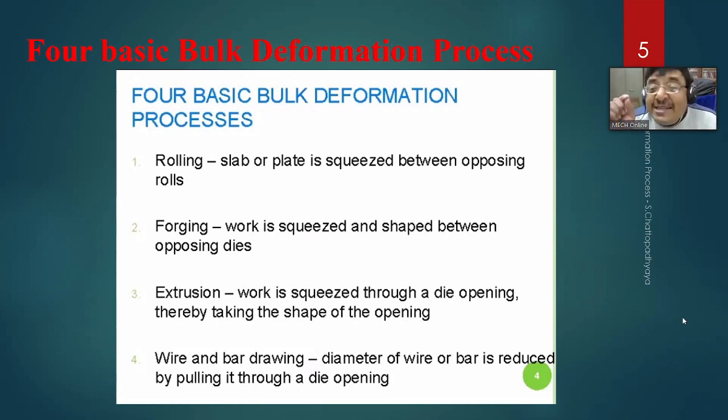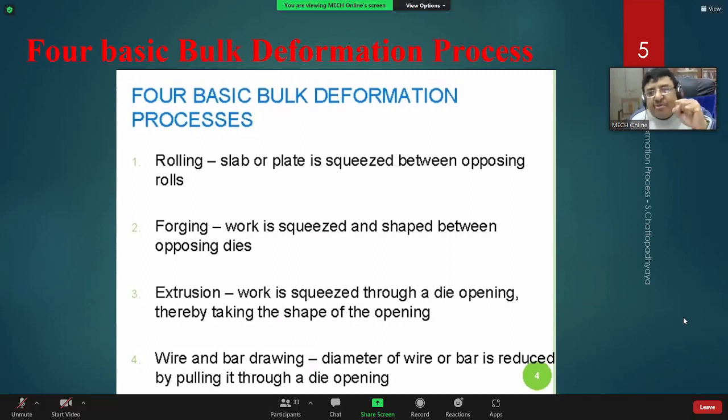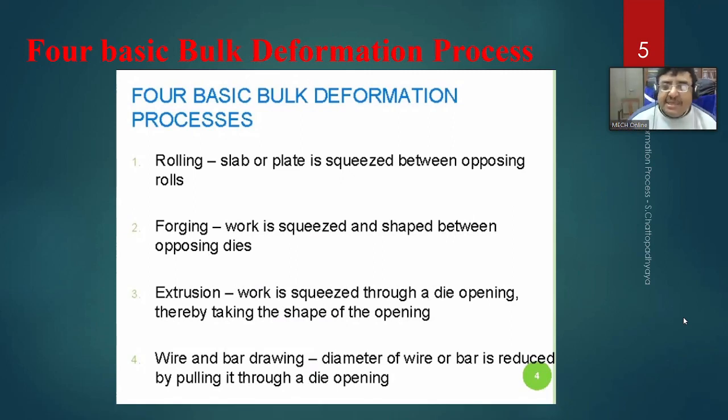So iterative process. Wire drawing is an iterative process, step by step. Suddenly you cannot just go for that amount of reduction, step by step, stage by stage. Otherwise, because of the shock, there is always a terrific chance that there will be a crack and the crack will be initiated. Clear, students? From thicker, step by step.